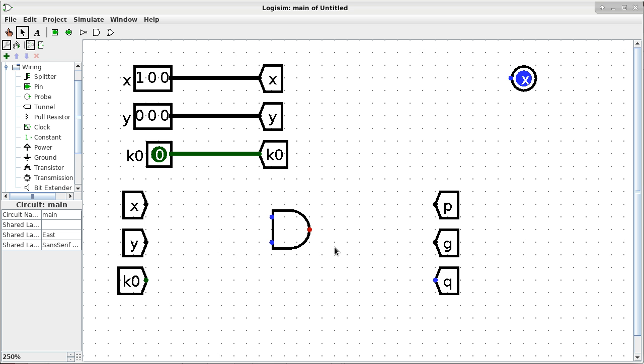Why? What happens in real life when you have a logic gate that has 5 input pins, but you only connect to 2 of those input pins? What happens to the other 3? They float. Very good. Okay, so float is the correct term in electronics. But what does it really mean? It's neither specified to have a high or 1 or low, which is a 0. So it's really just kind of hanging in between.